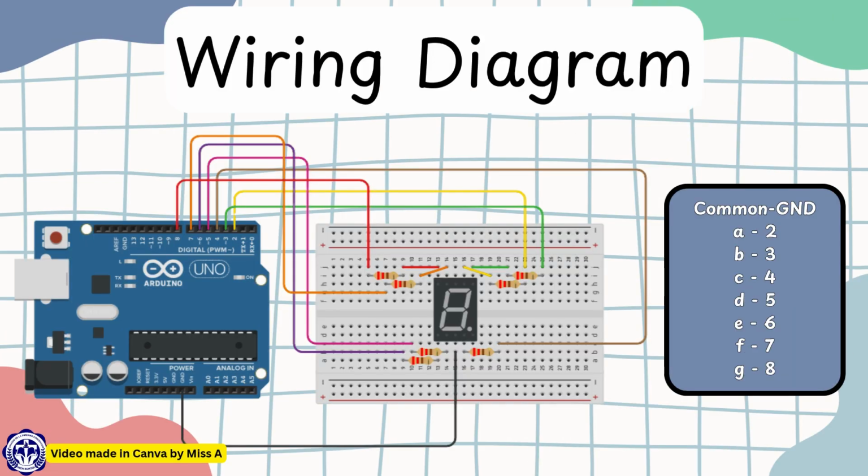To wire the 7-segment display to the Arduino, begin by connecting the GND pin of the Arduino board to the common cathode pin of the display. This establishes a shared ground for all segments.